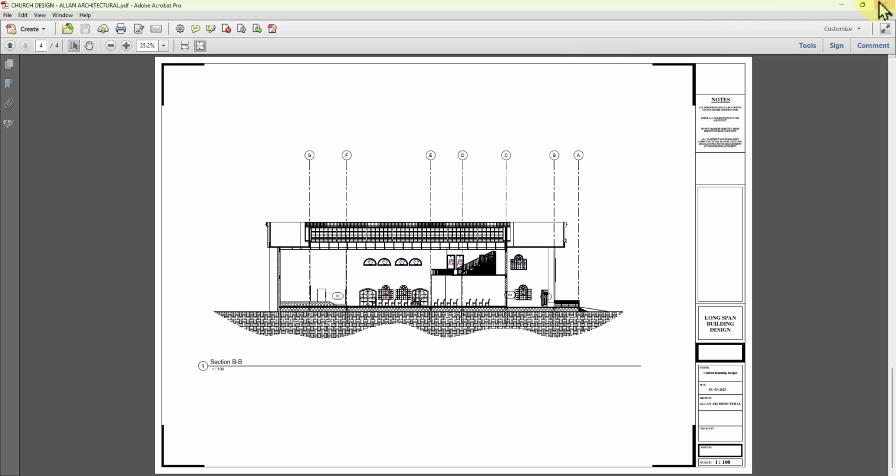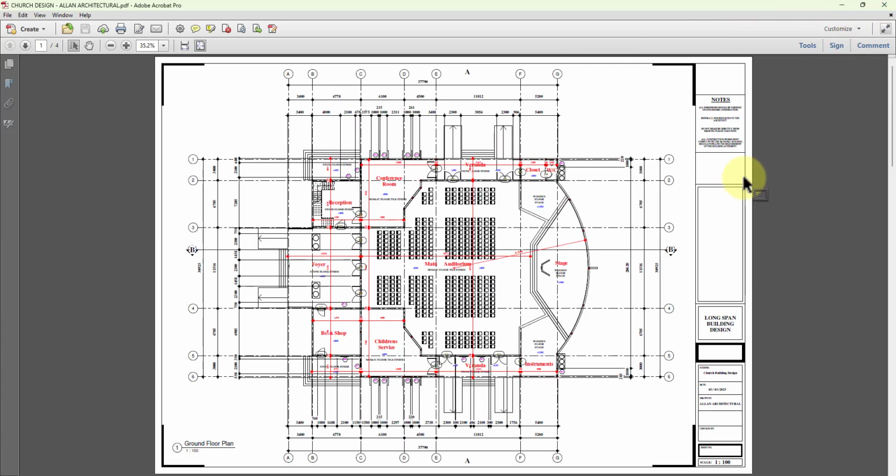So that's how we are able to combine stuff in Revit automatically. All right, so you just make sure you place all your views on the sheet, and then you go into combine files, then you select all the views that you want to be combined, and then you just click on the OK button, and then you just save that wherever you want to save that. So this is it for our final episode.